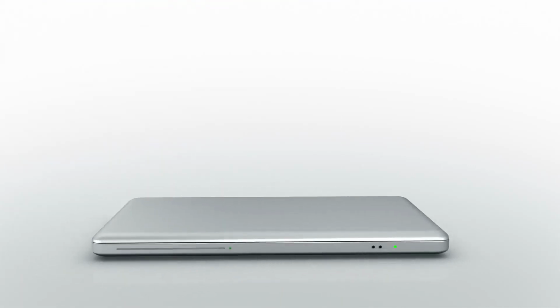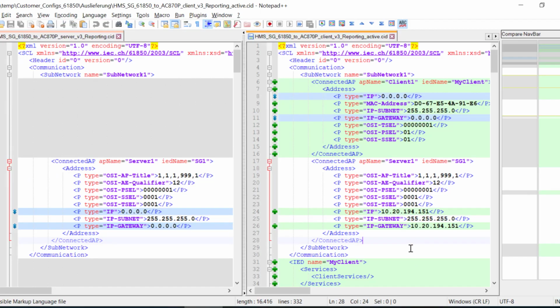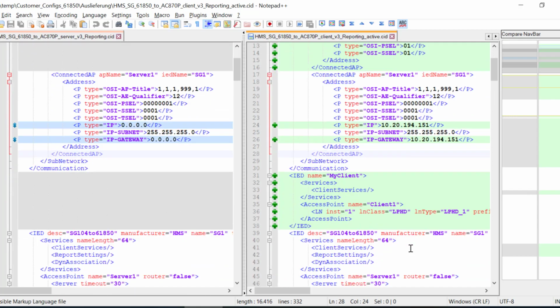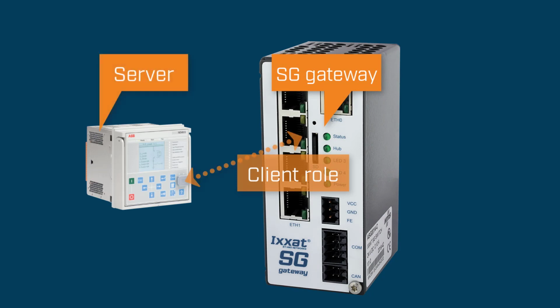To use the SG Gateway in client role, some extensions are needed, as a client is using its own IP settings and IED block, but also needs to import the configuration of one or more servers. Let's show this case based on a protection device, in our case an ABB REF615.